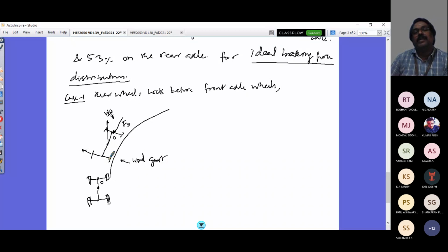The smaller disturbance in a vehicle from the side would precipitate this event. And here you see this couple is going to be this distance. If I extend this distance initially collinear, this distance is 0, but then this distance increases, and that would become maximum at a 90-degree turn, and then again it would start decreasing. But by the time you realize, in no time you would see that the vehicle has reversed in its rotation. So this is your rear and this is your front, and it would be completely rotated.